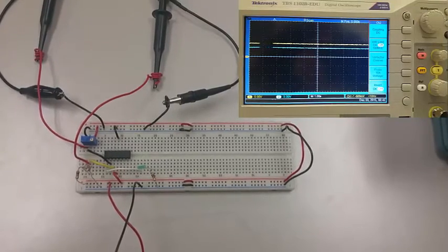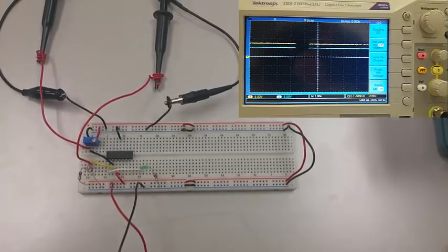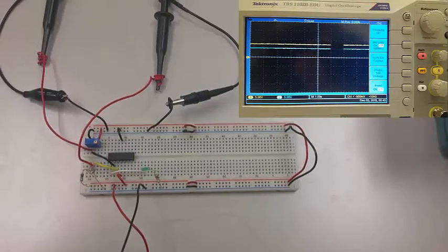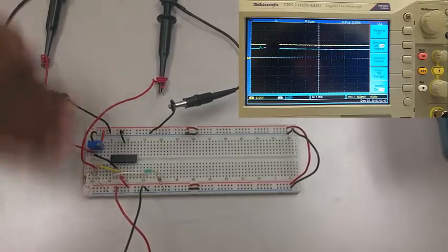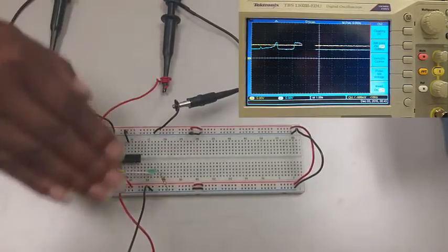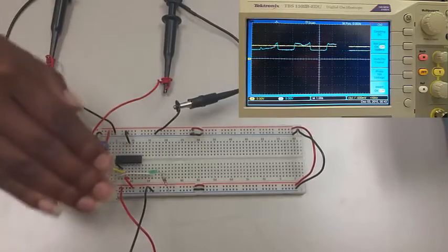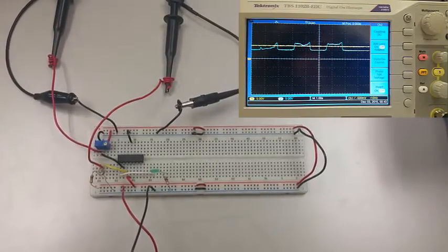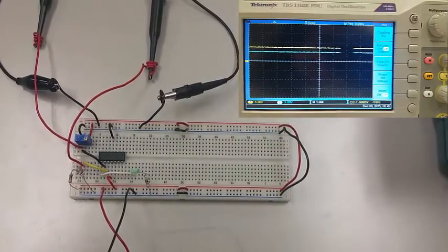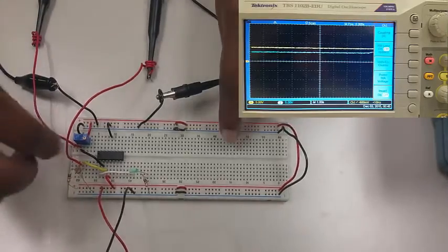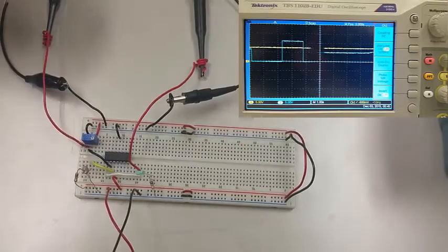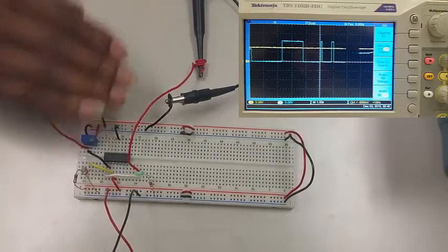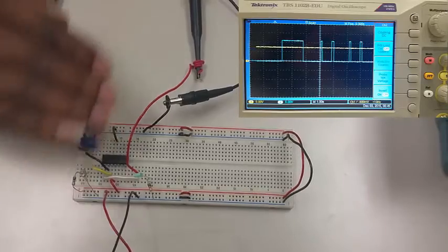To troubleshoot subsystem 1, we will connect channel 1 to the trim pot and ground, and channel 2 to the photoresistor and ground. Whenever I wave my hand across the photoresistor, we can see how the waveform changes. We expect the voltage to increase because the resistance increases. Now I will check the output of the LM324. This is our expected waveform.